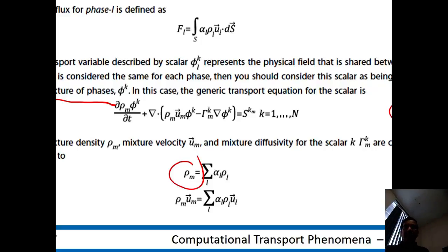So when you have multi-phase mixtures, gas-liquid, for example, you need to also worry about interface mass transfer from one phase to the other phase. Examples would be you're producing steam in a boiler. So you're heating up water, it changes phase into steam. So you have two vapor-liquid phases. And there is an equilibrium model that you need to worry about at the interface transfer. So at the interface, there is mass transfer.